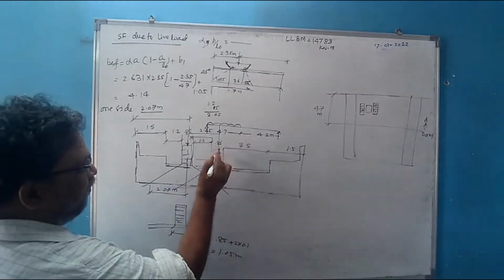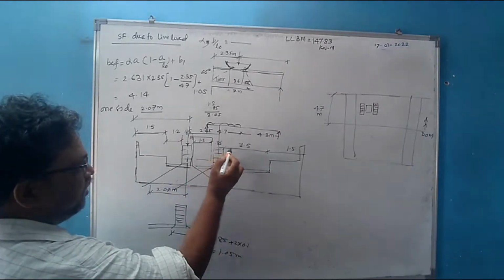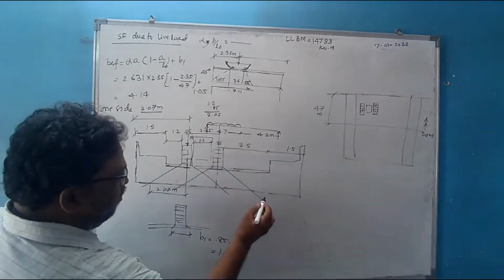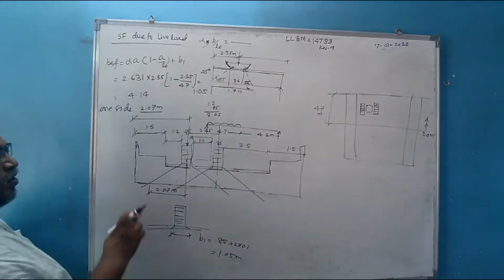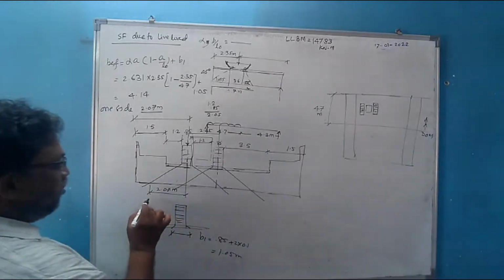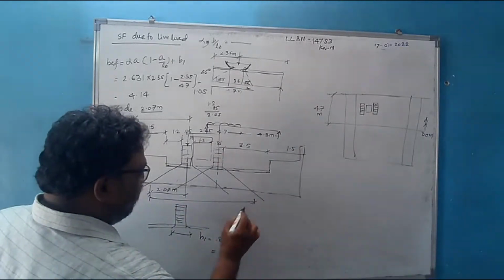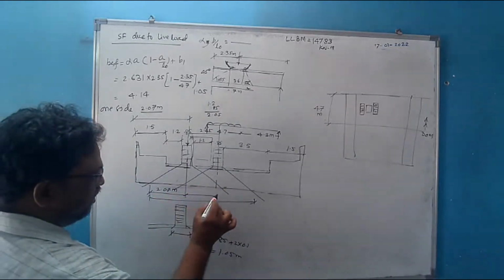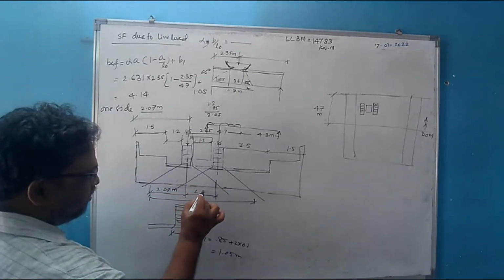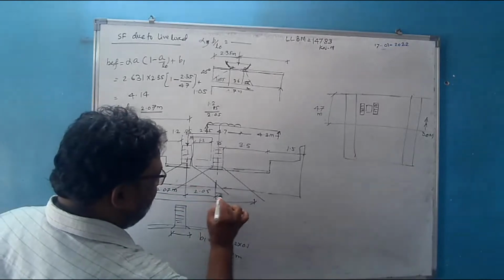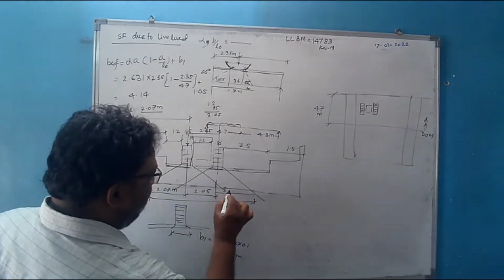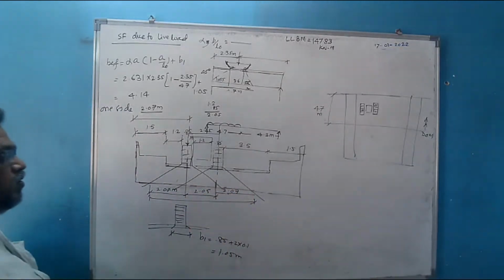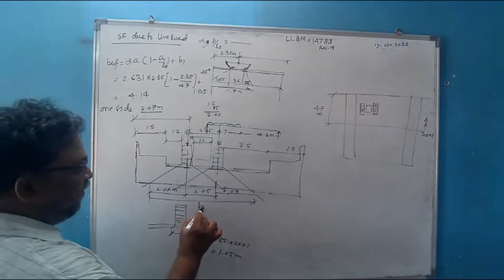This is 3.5 meters, and looking from here it will be a bit more, so it will not even reach the footpath. This load will exit from here. So this is the entire width on which the effect of this load will be. How much is it? This is 2.07. The center to center distance will be 2.05, and this side again it is equal to 2.07.